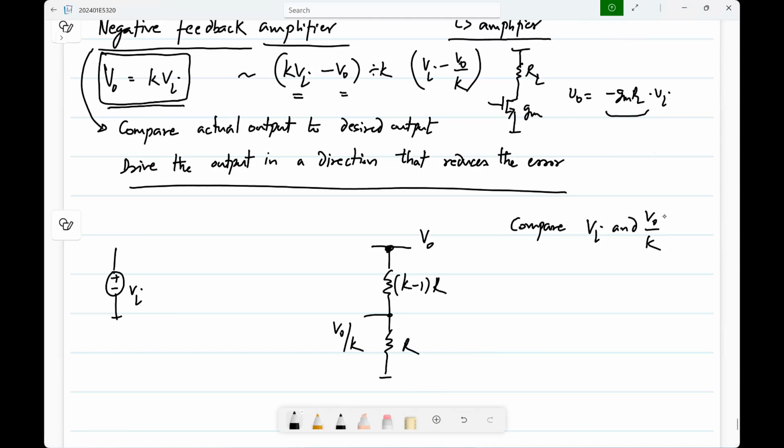We are making an amplifier, so we assume that K is greater than 1. Well, correct, but then do you need to make a circuit? That's the question. If K is less than 1, it's an attenuator. You may not need to have amplifiers and so on to make that. You may be able to do it in a purely passive way. Okay. But yes, if you do have gain in the feedback network, you will have attenuation in the closed loop system.